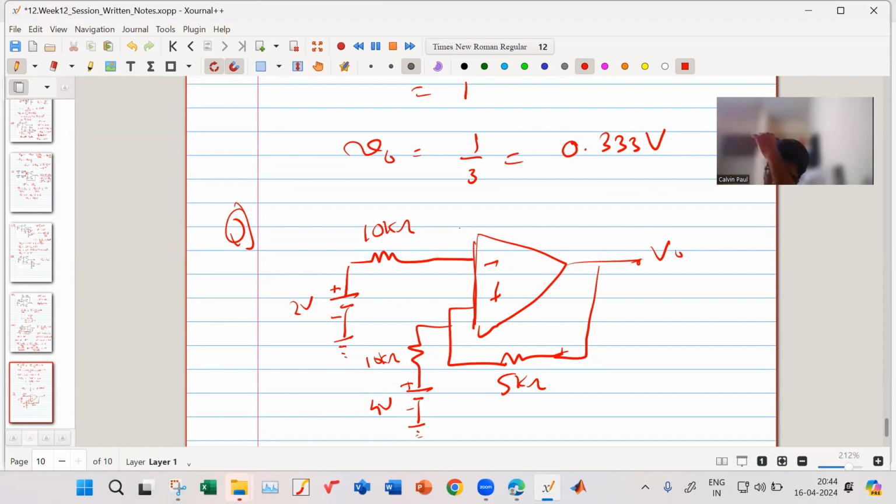So that is for the negative side. Your input is 1 volt, and you have 2k and 2k, so that is like a potential divider network. So the negative side input is half a volt. And on the positive side, the supply voltage is 2.5, and the resistors are 2k, 2k. Feedback is also 2k.